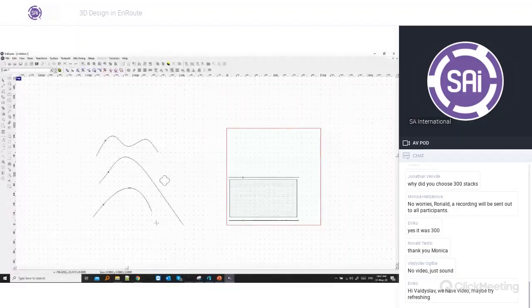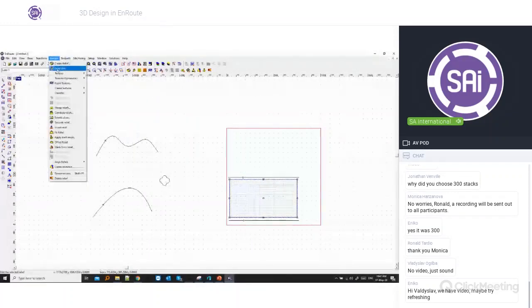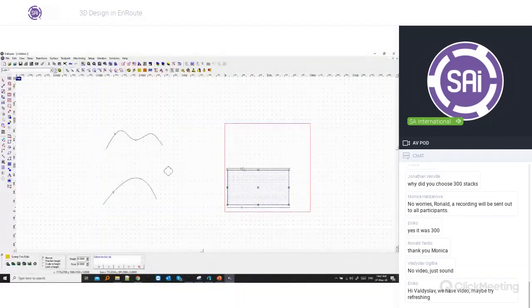Like this. And you can select multiple ones on the same sweep section multiple times. So it will become a bit more clear in a second. So I'm going to modify this relief. So I will select it, choose sweep 2 rails. I'm going to select this rail and then the second one. Of course, the rails have to point toward the same direction or you will end up with a very strange looking relief. So I'm going to select the first sweep section.